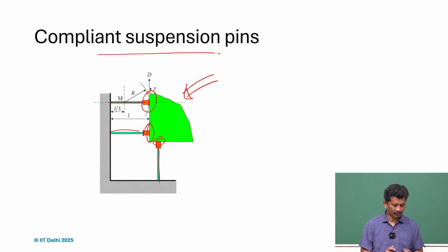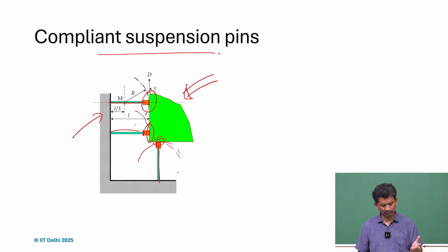Of course, we have to make sure that the deflections are small. And what we also learned is that if we take just one compliant member or a strip or the leaf spring, it's 1/3 from this one and 2/3 from the end. So it will be equivalent to a kind of spherical ball. So be aware of that, and accordingly we can design. But yes, compliant mechanisms can always come to the rescue and can help.